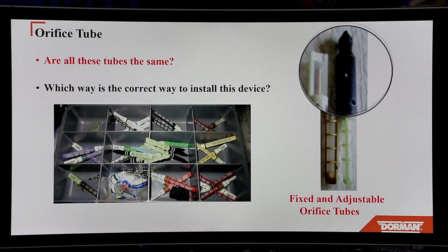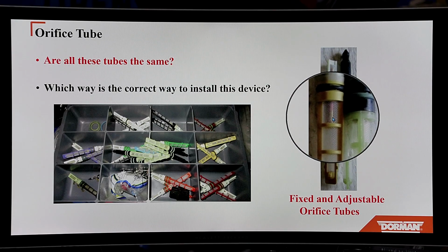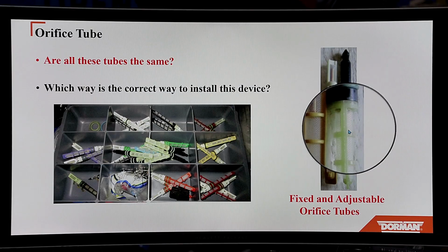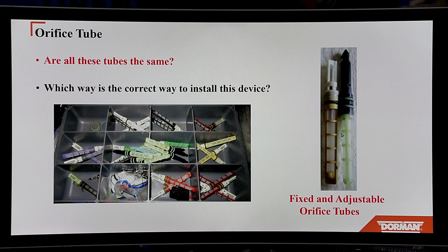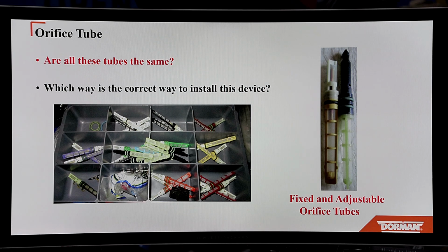Go for extra money, and you see this one here? This has a thermo bulb built in the end, and this orifice changes, not from a fixed one like this, but it changes from smaller to bigger. You will get better cooling. This is now on newer vehicles, and they've been installing them for quite a few years. So many of these, we don't use them anymore. You know, I have them upstairs, but you're way better off putting the right one in.